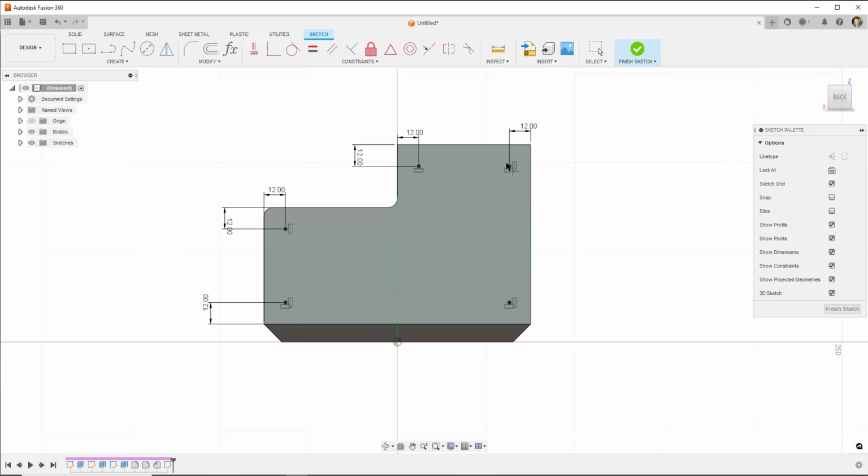And these alignments, it kind of put them on automatically, but they're called constraints. And if you ever want to view them or edit them, you get these little symbols here. And if you highlight one, you might notice it highlights this one too. It's hard to see, but the items that are constrained together, their constraint symbol will highlight when you select the other one, if that makes sense. And if we wanted to get rid of that, we could just right click it and click delete, okay?